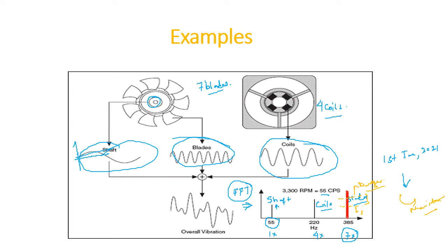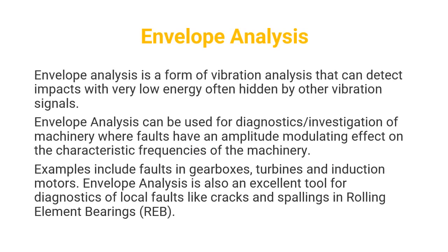So the next technique is envelope analysis. Envelope analysis is a form of vibration analysis that can detect impacts with very low energy, often hidden by other vibration signals.